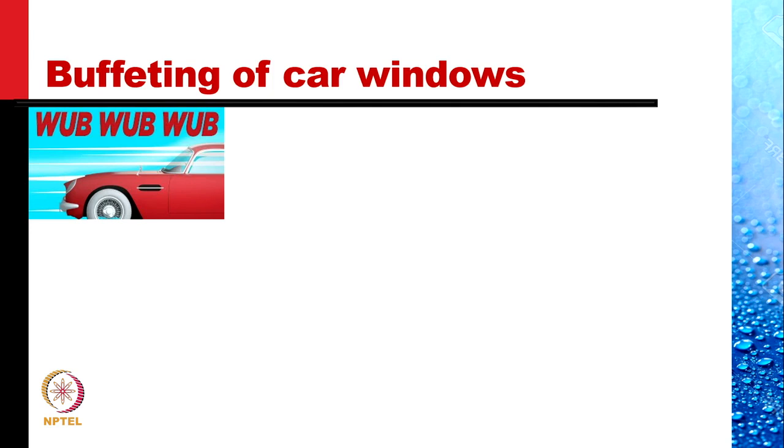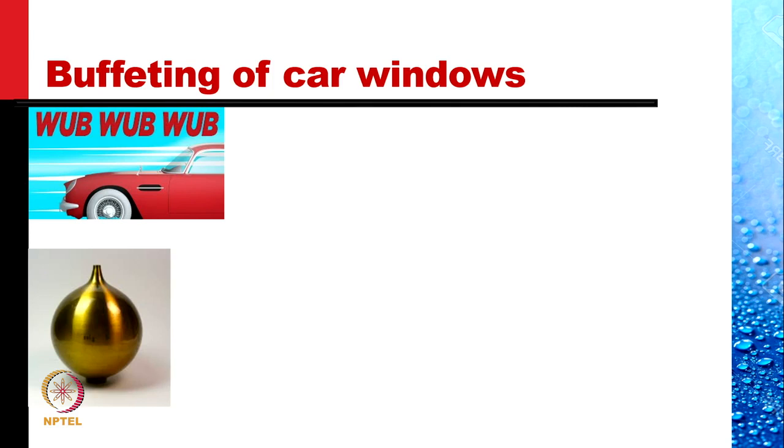And why is this happening? It's happening because of an interesting phenomenon known as resonance in a Helmholtz resonator. A Helmholtz resonator is a volume with a neck. The volume serves as a spring and the mass in the neck oscillates. Given a volume and given the neck dimensions, there is a particular frequency at which this resonates. And so you hear that sound.